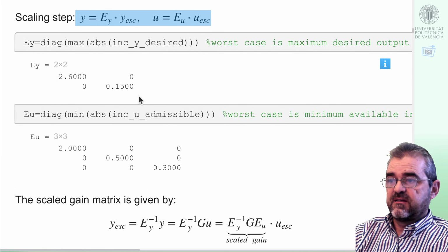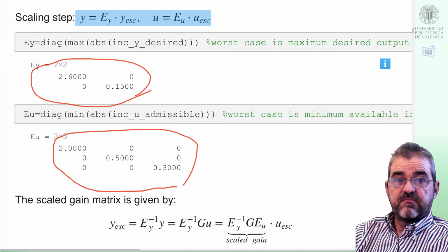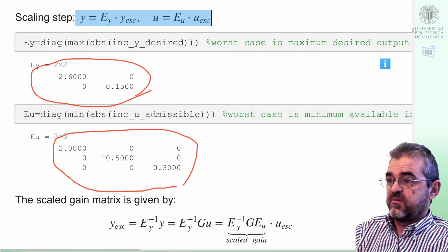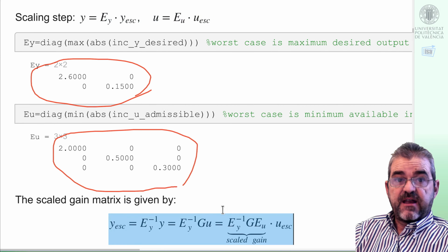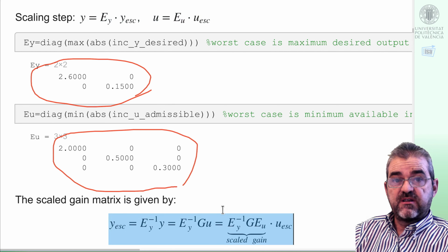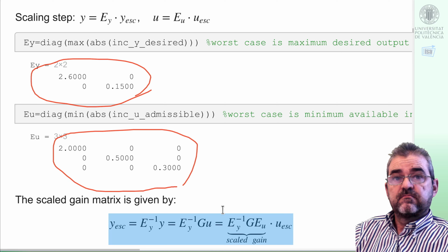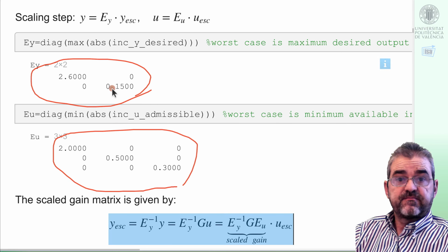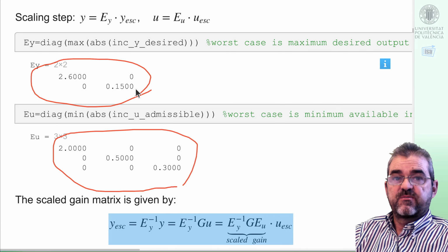So these are the scaling equations and the scaling matrices. In previous videos we did the change of variable to scaled units just with the DC gain. Here we'll do it with the full G(s), the full frequency response of our systems. For total disturbance rejection, output scaling EY will not be relevant in the computations, but as we are mixing setpoint tracking and total disturbance rejection, we'll keep that scaling in both problems.